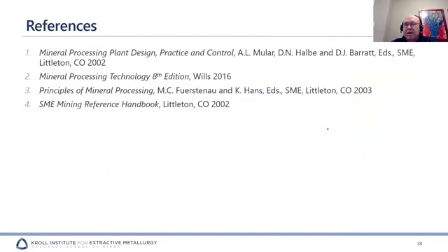And that's the end of the lecture. So classification, we do it with screens, we do it hydraulically, we do it in hydrocyclones. Classification is the umbrella term for separating coarse particles from fine particles.